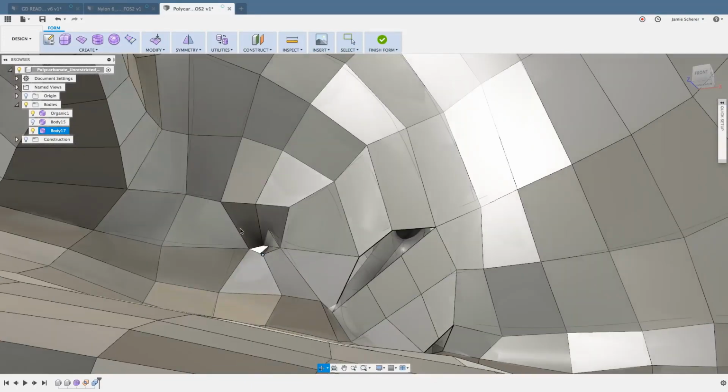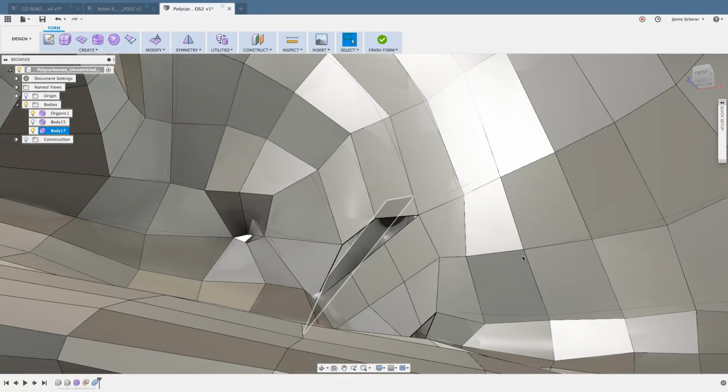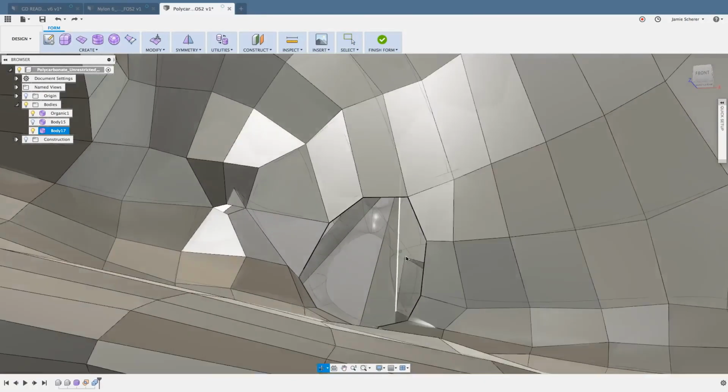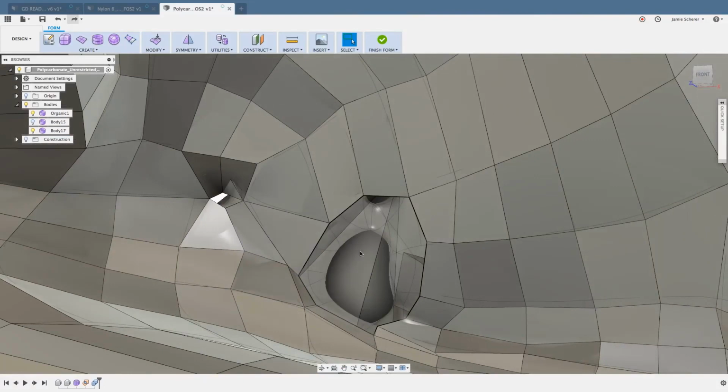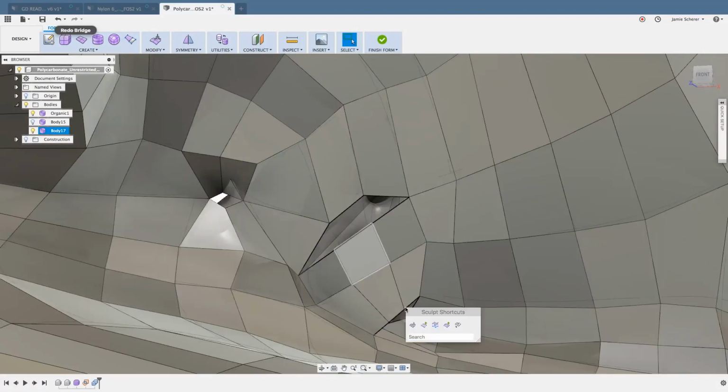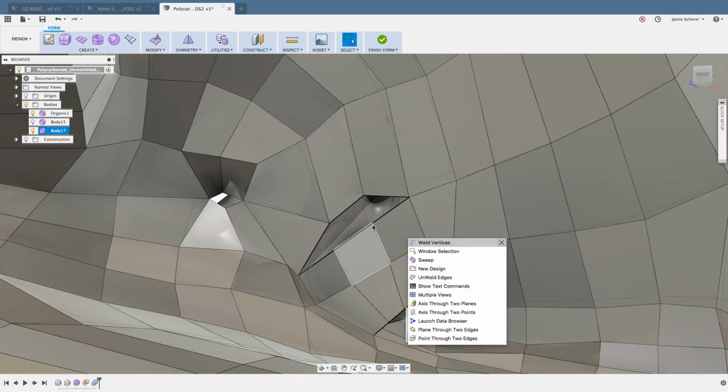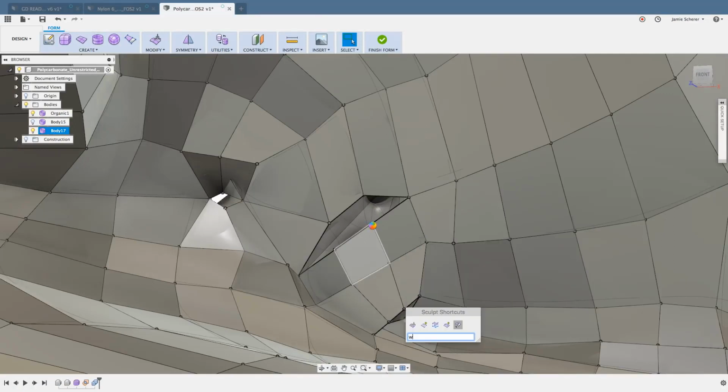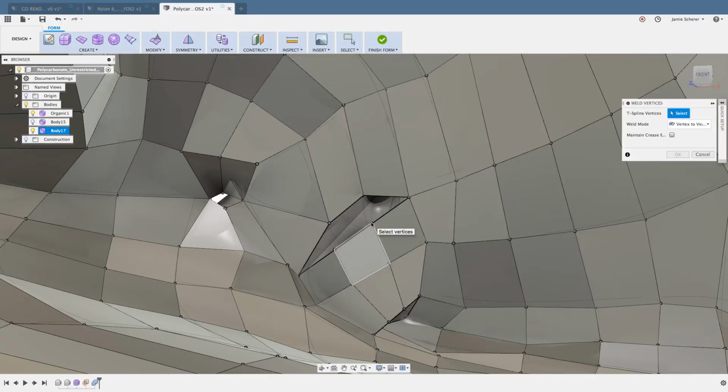So coming back around, you'll see, now I just want to go back and weld together those last faces. I'm going to go through that final step one more time, because I accidentally escaped out of it, and it's just weld first selection to second selection. So the first vertice moves to the second vertice, and we'll just do that here 4 times to make those selections. Got myself distracted by talking about what happens if you window select. It'll just weld together a bunch of unwanted vertices, and then you can either unweld them or undo. So just be aware of that.